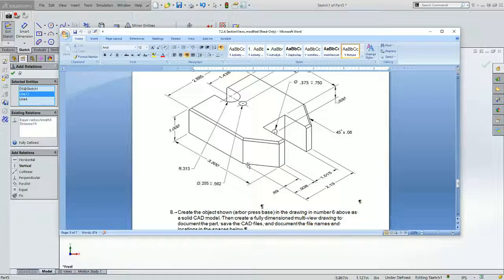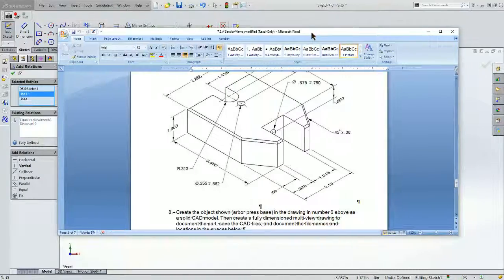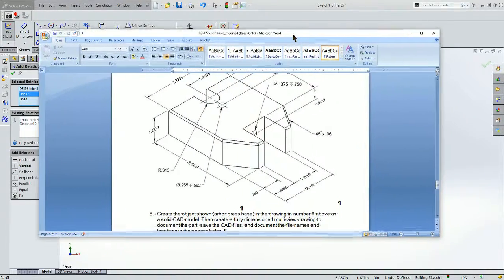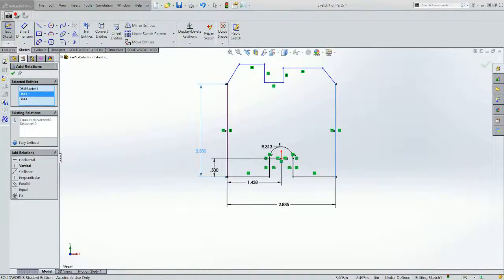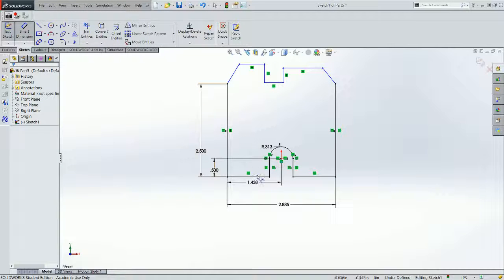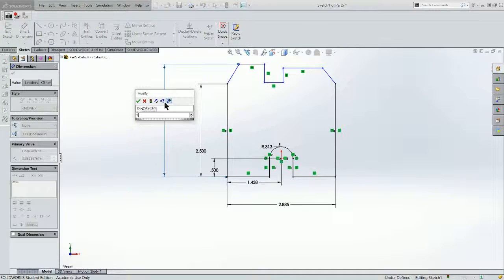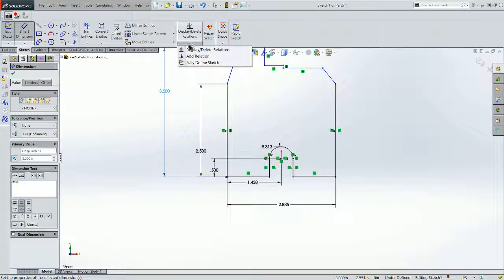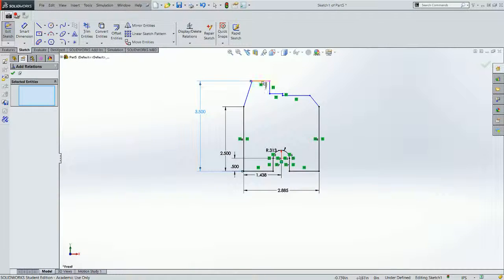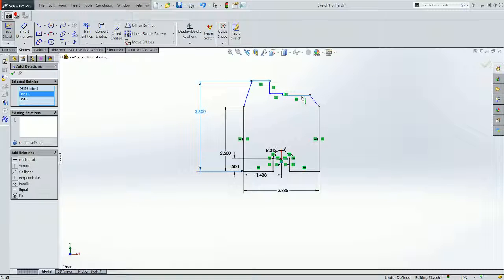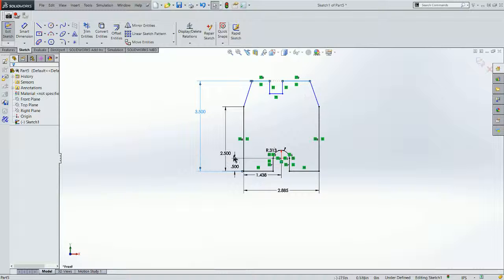Now I have to define this angle by going in 0.69 to the top, which is 3.5 rather. So let's add first my dimension, the bottom to the top of 3.5. Let me add a relation between my 2 lines that form the top, make them collinear.